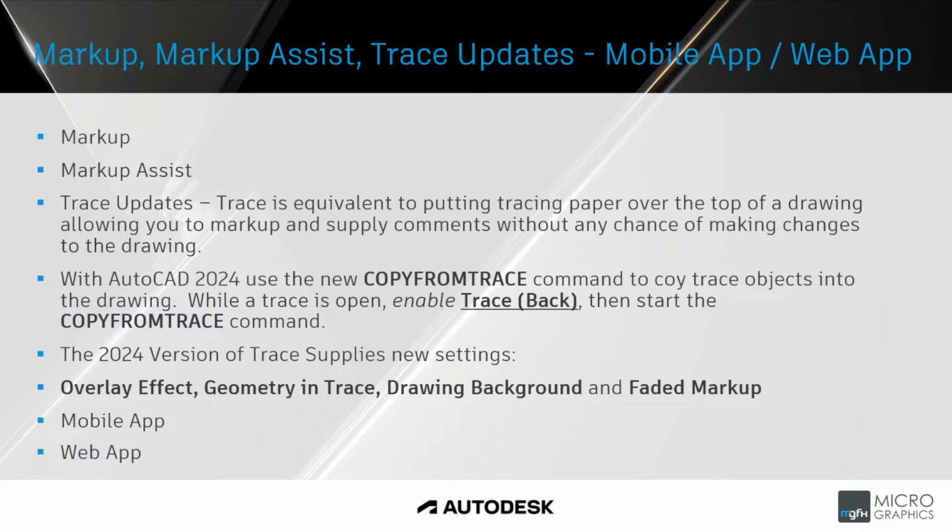The Overlay Effect is for adjusting the tracing overlay transparency. The Geometry in Trace is to adjust background geometry transparency. With Trace Front enabled, this affects the geometry in the drawing. With Trace Back enabled, this affects the geometry in the trace in the back.